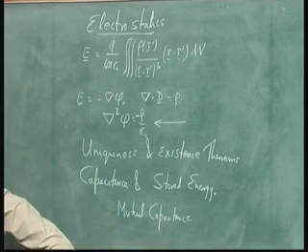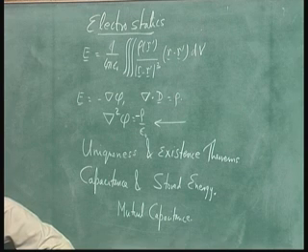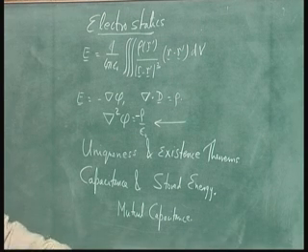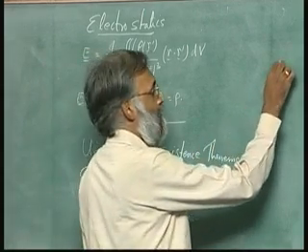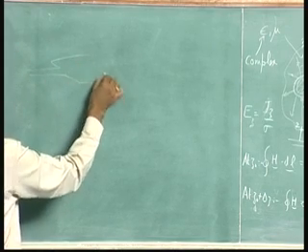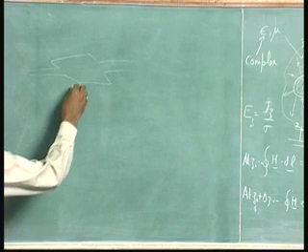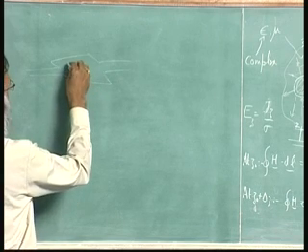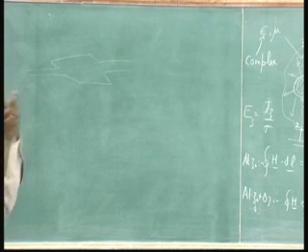This is perhaps not very important for power electronics and EEE in general, because it really comes up more when you are doing microelectronics, VLSI, RF boards, things like that, where you have a device, and the device has a capacitor somewhere, and the capacitance occurs not only between, say, the junctions of your transistor, but also with the substrate.